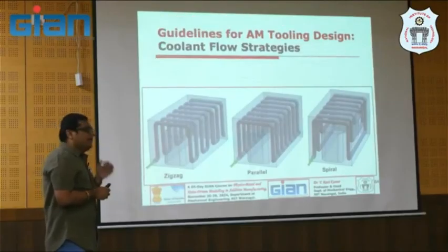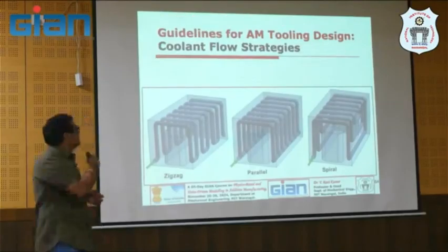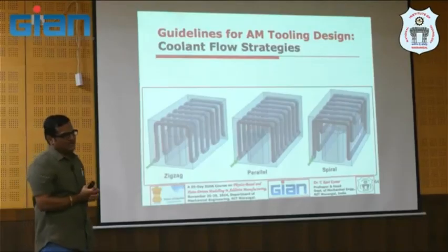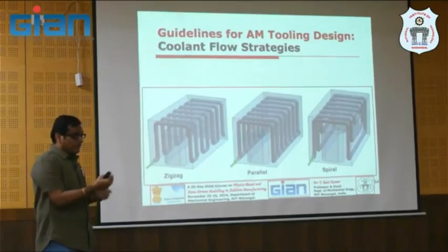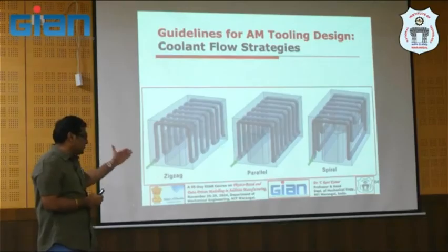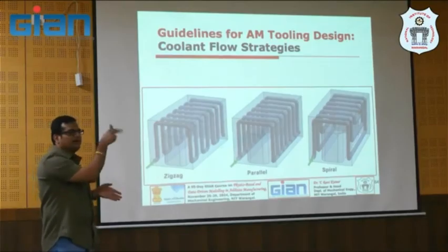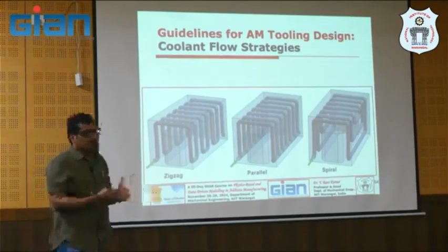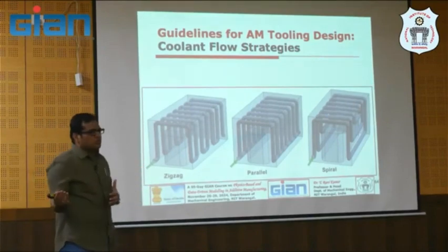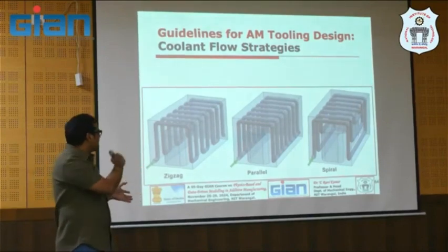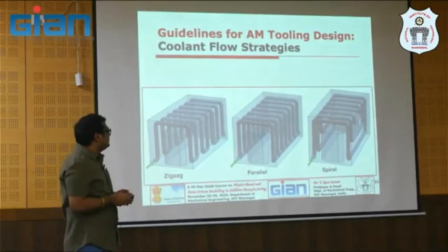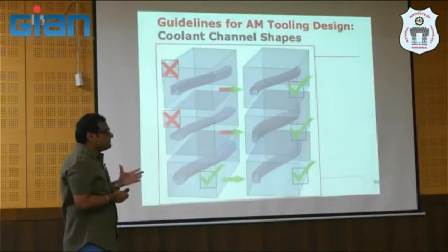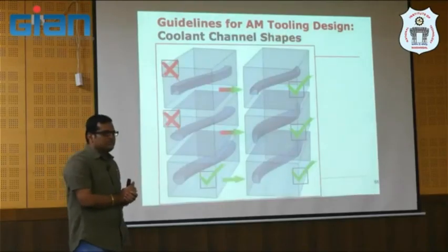Yeah, and the most important thing here is how you can design these flow strategies, right? So you can simulate all this. You can have the zigzag flow, or the parallel flow, or a spiral. Based on your tool design, you can optimize the flow strategies, as well as the cross section of your cooling channels, right?